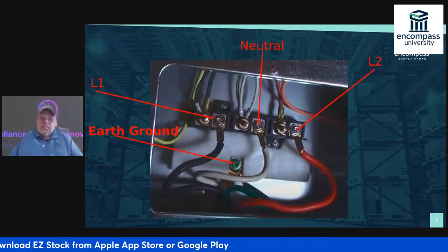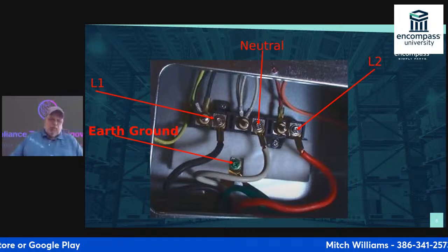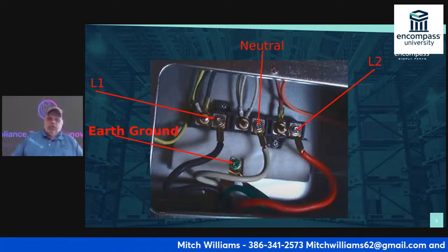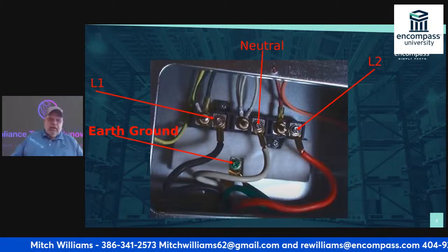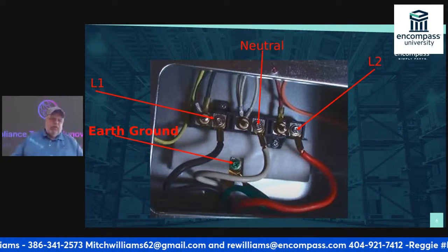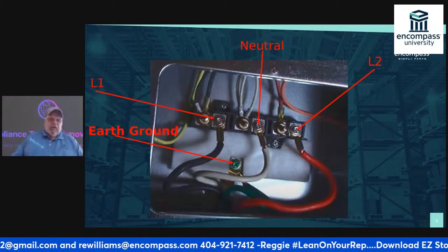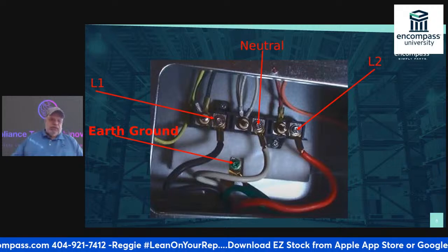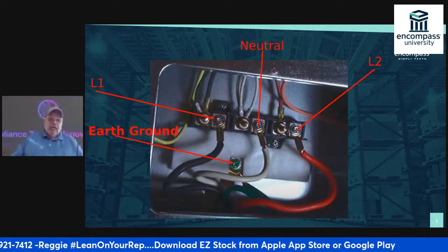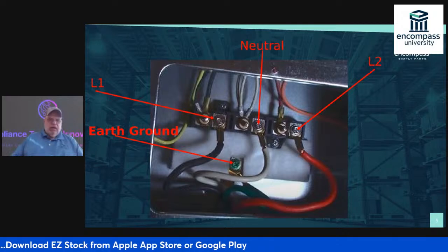Many of the companies today have a wire that goes between that screw and up to the center where it says neutral. You may have to break that wire off if I am trying to provide an earth ground. I should have an L1, which is a power lead, an L2, that is also a power lead, a neutral, and then an earth ground.